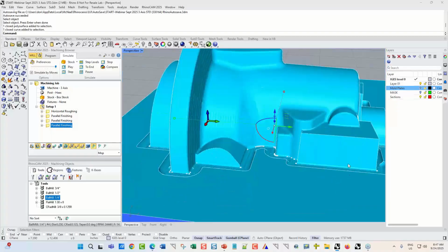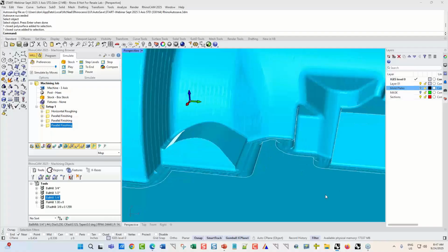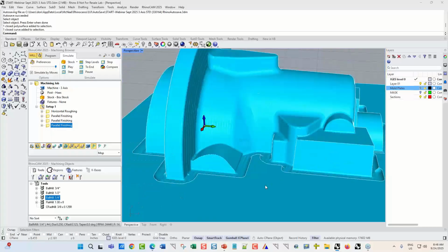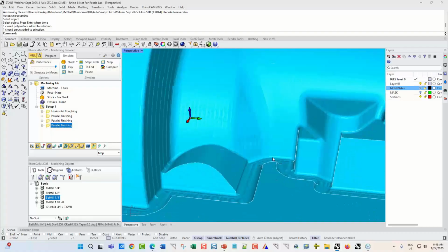And still we contained it, so we're not cutting any of this extra stock material. I think you'll see what I'm getting at here: we're working it down with a smaller tool. And then we're going to come back in at the end with a finishing operation to not only clear this parting plane, but also get a really nice fillet here.